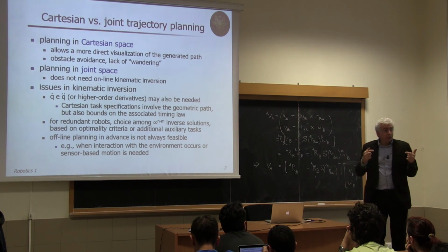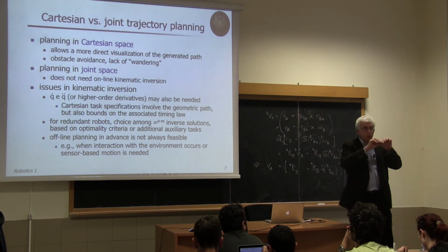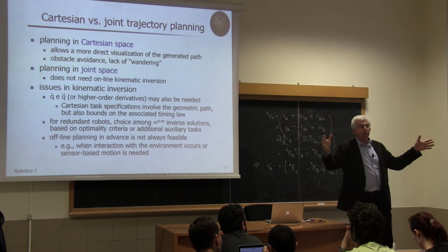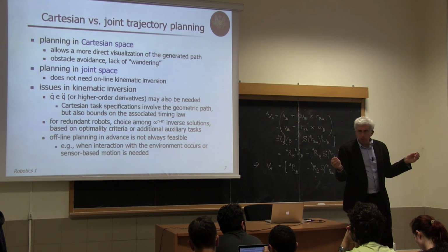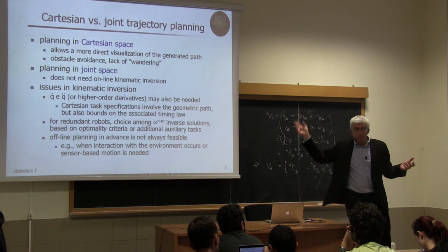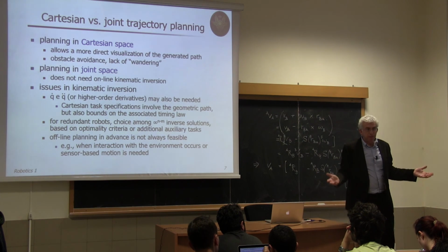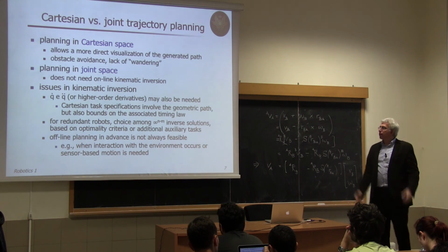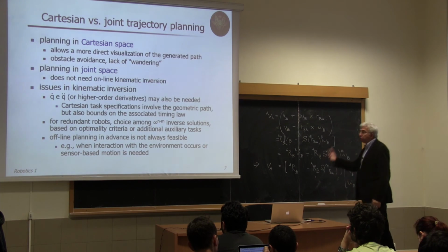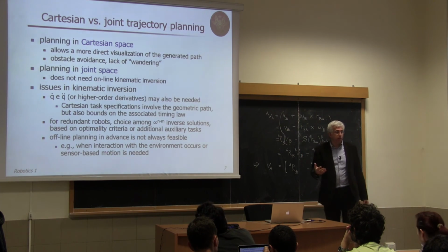While if I'm doing interpolation of very rare points in the joint space, what happens in between, even if there's a regular interpolation in the joint space, due to the nonlinearity of the direct kinematics, I may go around the points A, B, C in an unpredictable way. Okay? So there is this risk of wandering out of a natural motion. Okay? And overshooting, for instance, on the final destination.